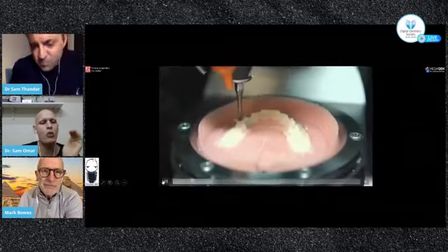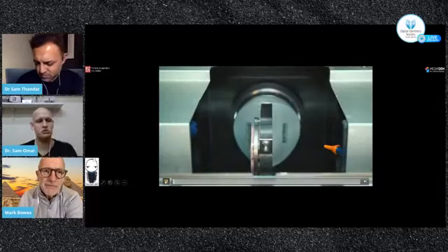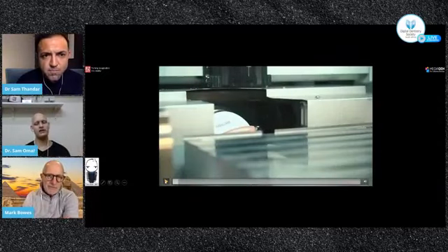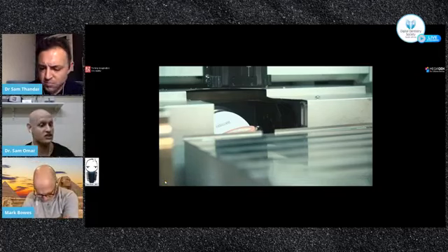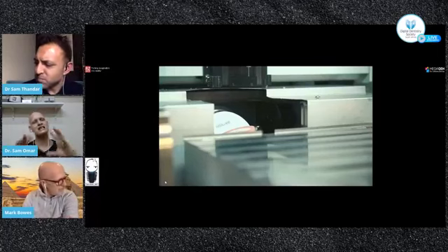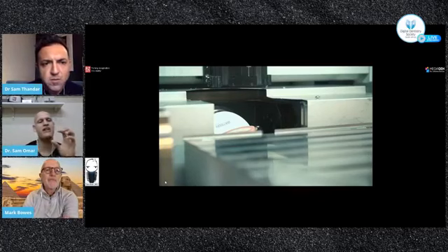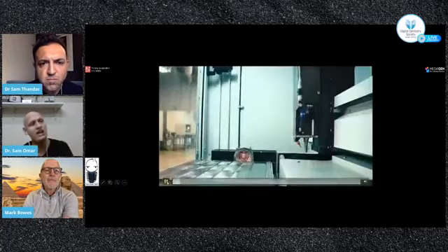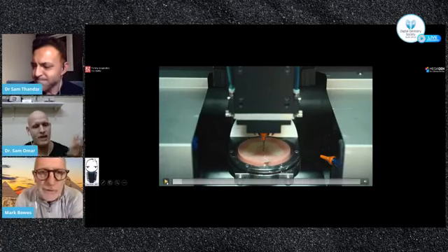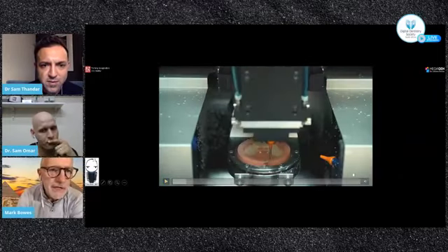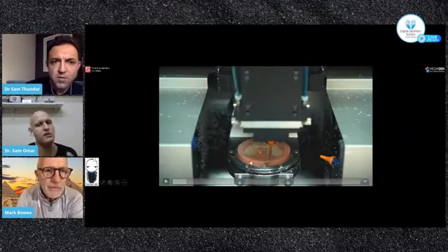Okay. So basically, they have a very cool protocol when it comes to the manufacturing. They believe in monolithic dentures. They have two-piece dentures and monolithic dentures, but they believe that monolithic dentures are the way to go. So they design the denture first, and then they go through a specific manufacturing process where they manufacture a puck or a disc for every patient. And that's the key part. You see this disc right here, it has both the white part and the pink part in the same puck. And based on that, what material is that, Sam? This is PMMA. This is cross-linked PMMA.